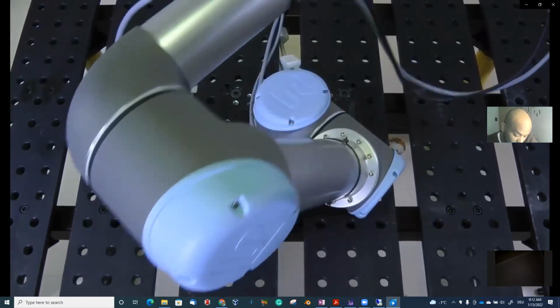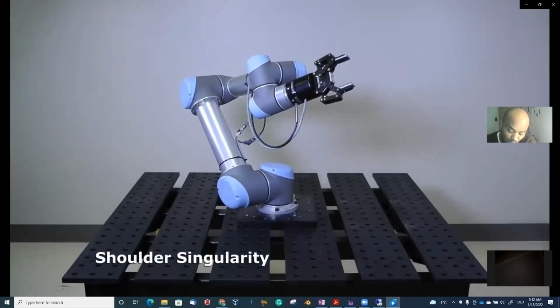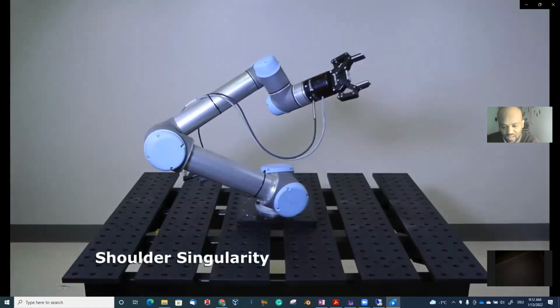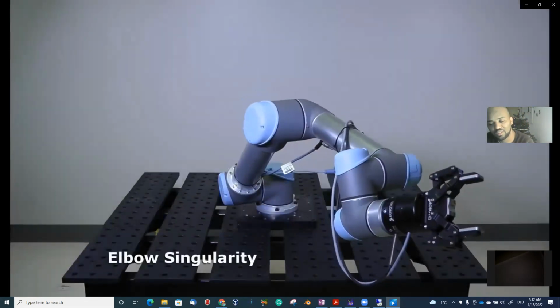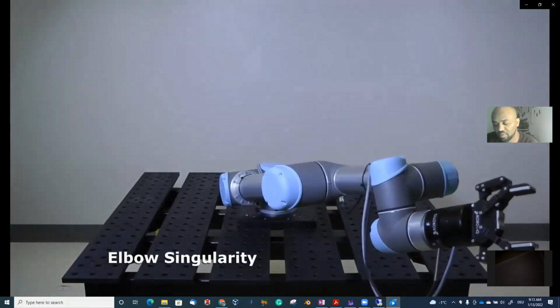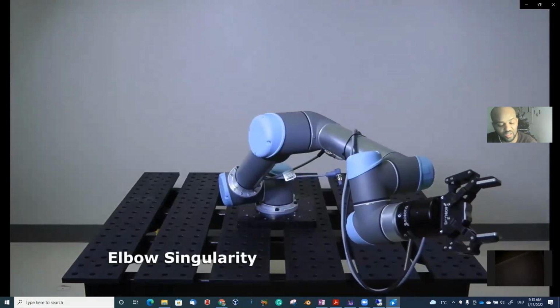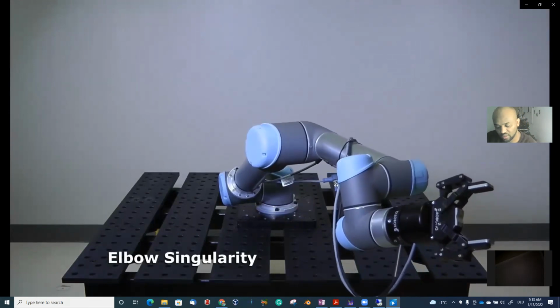Actually, this happens when you have inverse kinematics. If you have forward kinematics, you already have pre-calculated joint angles. You say theta 1 is 90 degrees, theta 2 is 50 degrees, and so on, so you define them.